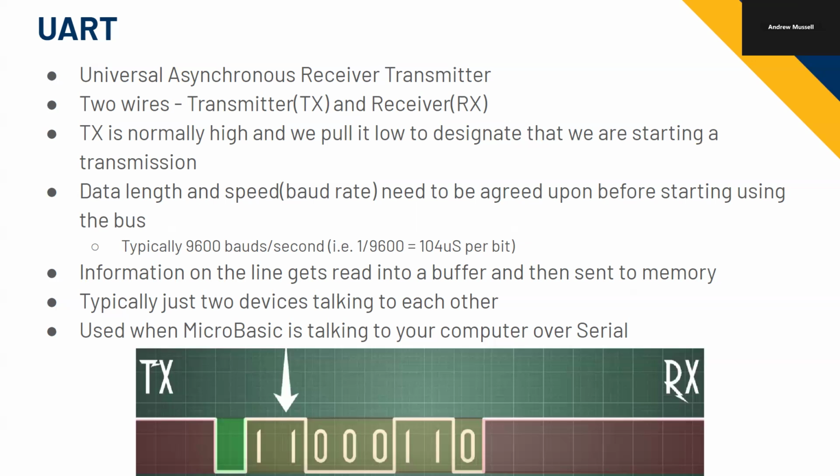Imagine I had 8 boxes behind me: I see the first bit and put it in the first box, then the second bit in the second box, the third in the third box, until you get 8. Then you take all 8 boxes and put that into memory. That's how I'm turning it from serial, one at a time, to parallel, 8 in a row. It's basically just collecting.